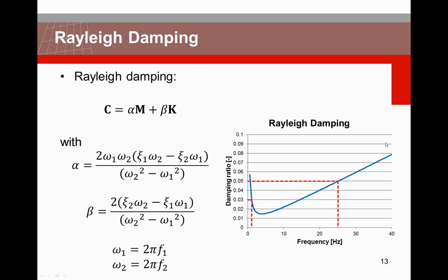These two points define this curve. A Rayleigh damping curve always has two asymptotes. One is at 0 Hertz, the static one, so it goes to infinity on this side, and the other one, related to the stiffness, is a linear one starting from the origin and going in a diagonal way. The Rayleigh curve is always fit between those two curves. If you use these formulas to find your damping ratios, you will always find that your alpha and beta have non-zero values, and even always positive values.